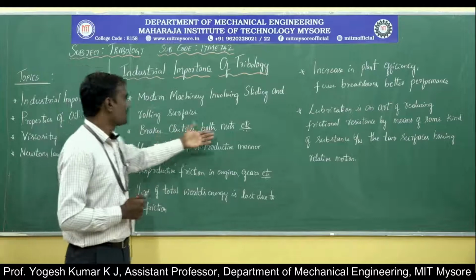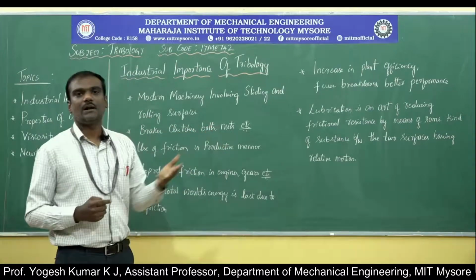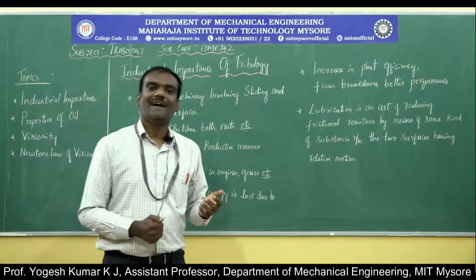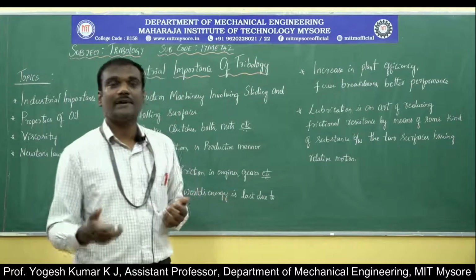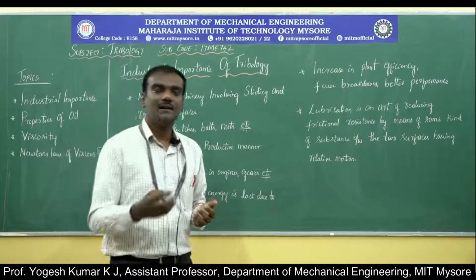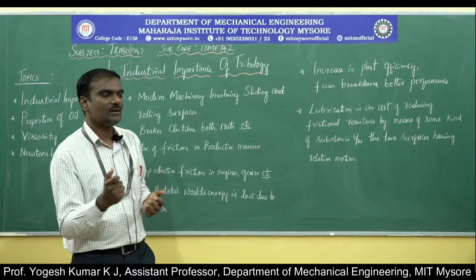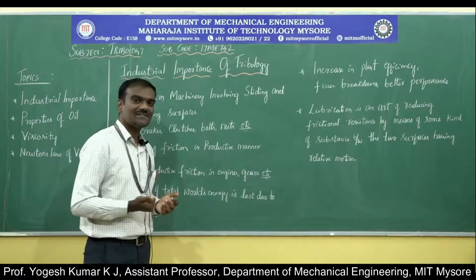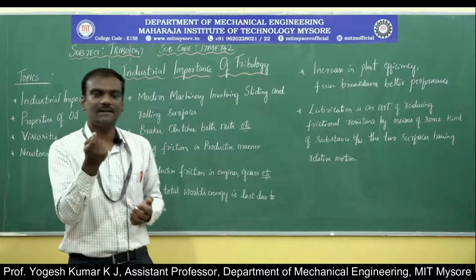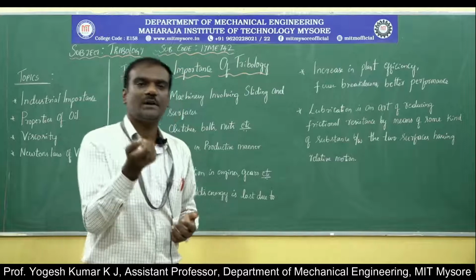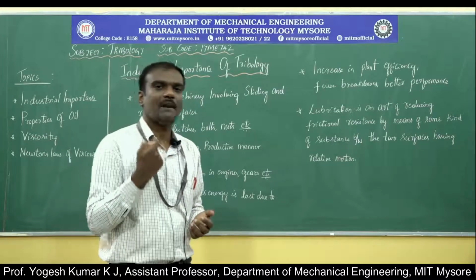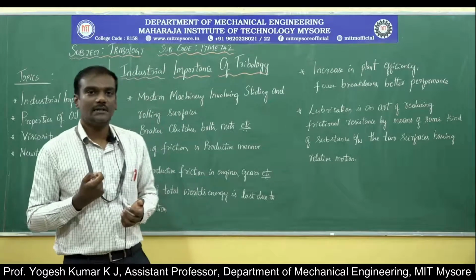Nuts and bolts: we might have seen a bolt and nut getting loose. This happens because of vibrations created in a vehicle, and that small disturbance removes small particles from the nut due to fretting.